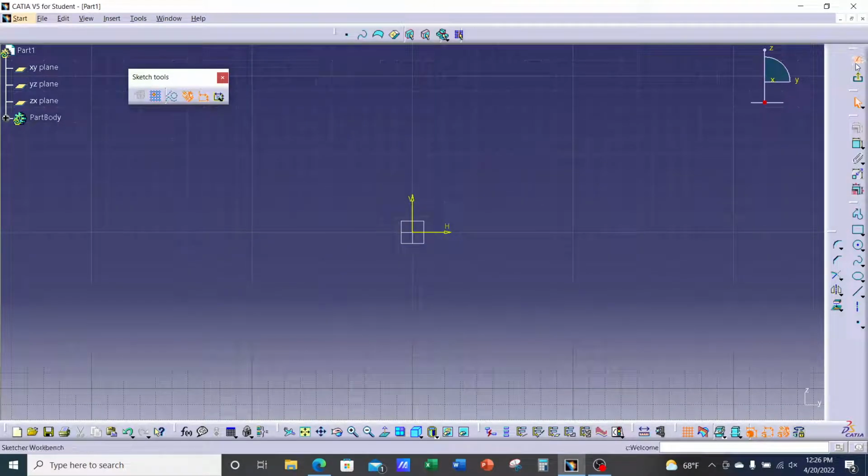Okay, now we are in Sketcher, right? We are in the Sketcher module or workbench. If I hit the plus on the tree, notice we have a sketch. This should be sketch 1, but remember earlier we first started creating a sketch. That would have been sketch 1, but I exited without creating geometry. So the next default name is sketch 2. Don't worry about the name. We can always change it if we like. We can always right click properties and change the name.